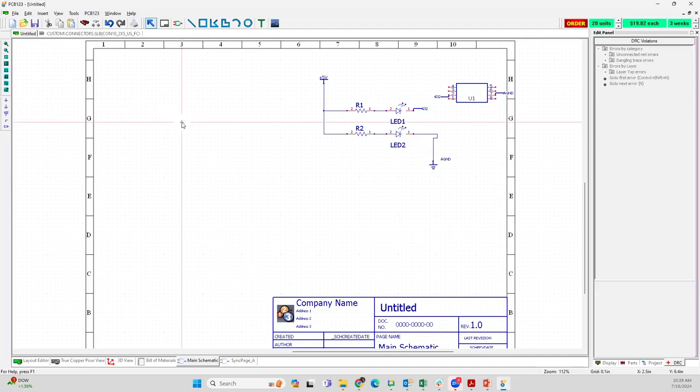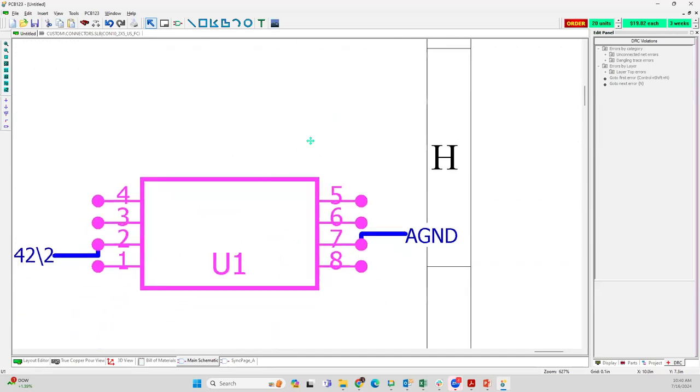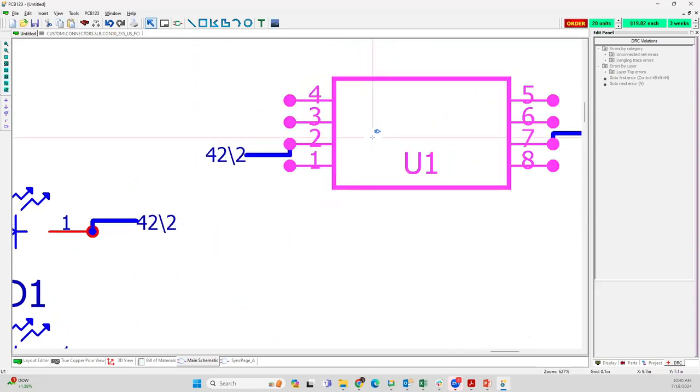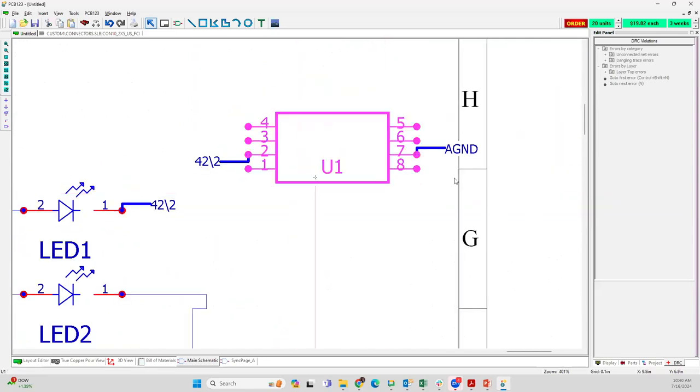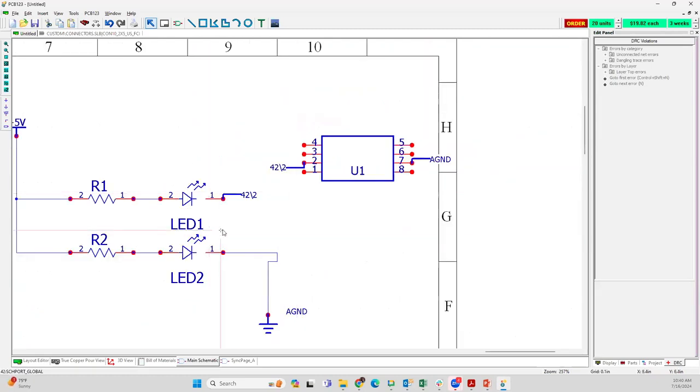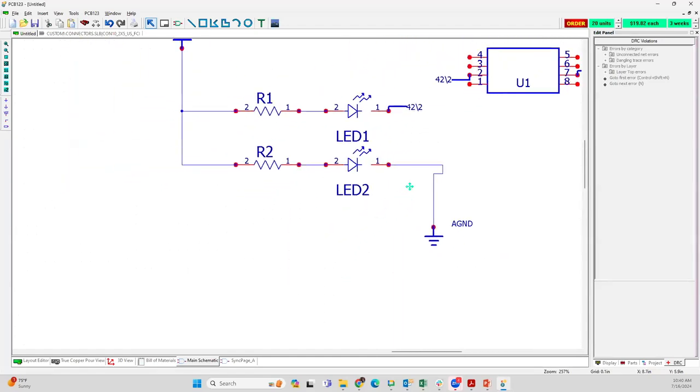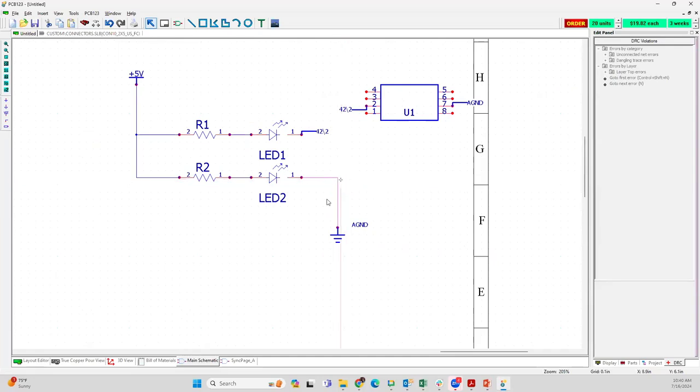I tend to not. It makes a design. It throws a lot of parts on your board. You have to coordinate the footprints with the schematic symbols. You can't read the schematic when it's all done because it just drops a bunch of symbols like this tied to your parts. When I edited the footprint, it changed my symbol to a generic symbol and hooked up just basic net symbols to it. In order to get those to tie back correctly, I would have to go in, delete the symbols, hook up the wires, and clean up my schematic again. So I don't like to work like that. I don't like to change my footprints on the fly.